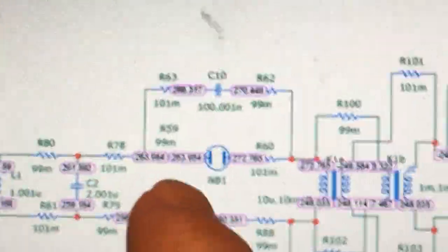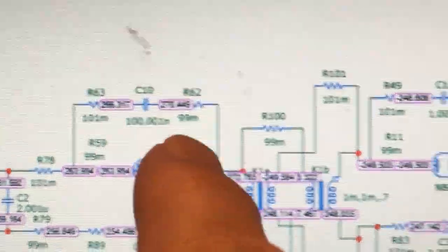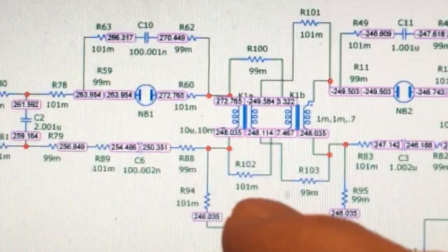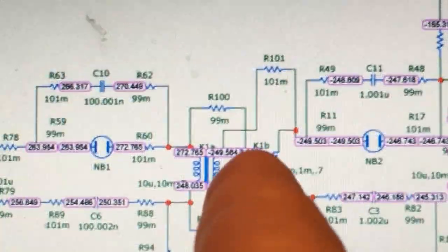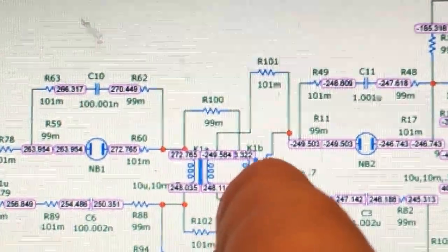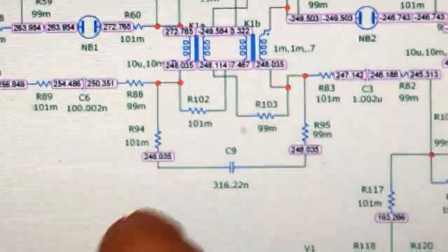Now I have a lot of little resistors of 100, 101 or 99 milliohms, and that represents a very bad solder joint. So I want realism as much as possible, so I put in solder joint resistances. And I doubled my transformer. Usually use radio choke coils, but then you short it out between your modules. That's the way Eric Dollar does it. I learned not to short them out unless I want to enhance it, so then I put a capacitor short